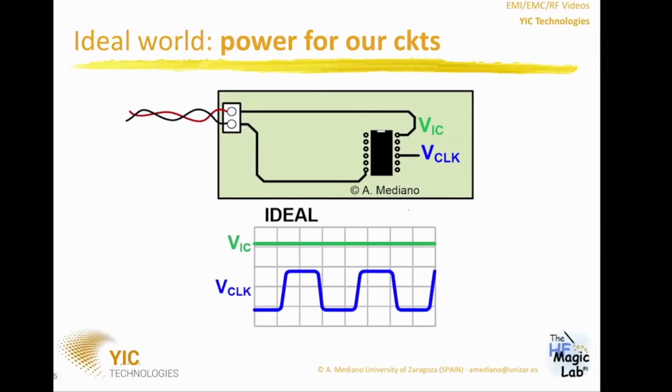So we have a circuit. Consider in my slide, this is the black integrated circuit. It could be a digital circuit, analog circuit, audio circuit, radio frequency circuit, power electronic driver, any kind of electronic circuit that is active. You can see that we need some kind of power supply. Typically, we can think about 3 volts, perhaps 5 volts, perhaps 12 volts, any kind of DC voltage. And we have an output. In my example, is a clock signal. You can see a square wave signal with a rise time, a fall time, maximum amplitude, zeros and ones.